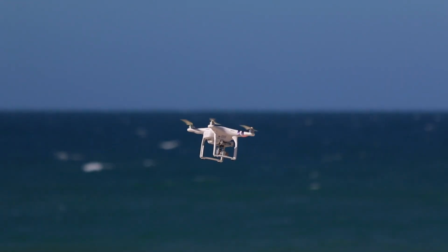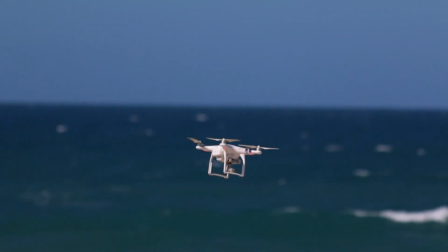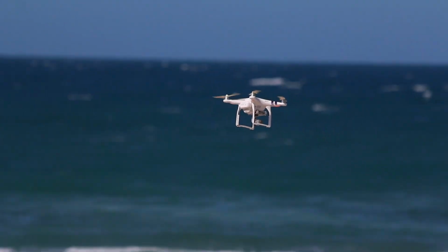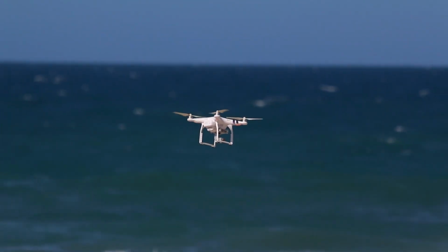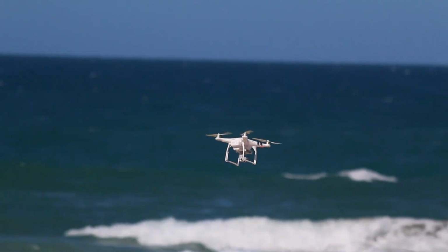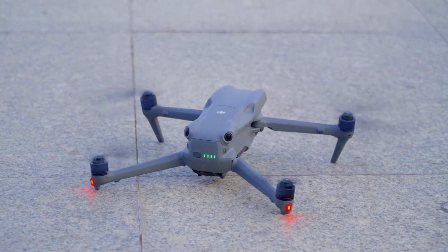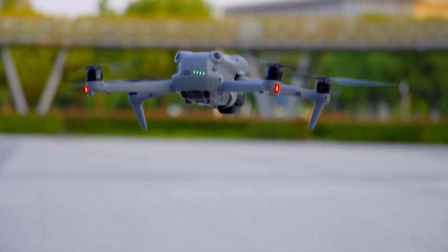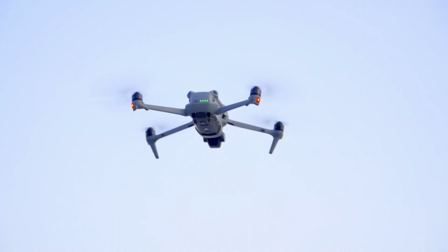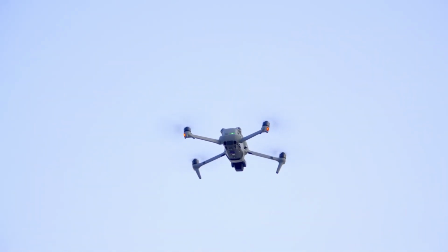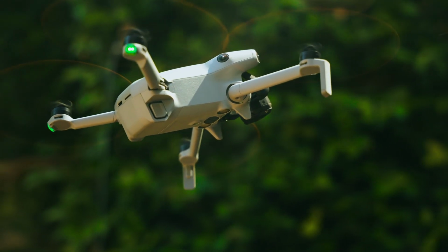Roll works the same way but sideways. Want to go left? Speed up the right motors, slow down the left motors. The drone tilts left. Instant sideways movement. And yaw, that's rotation. The two clockwise spinning rotors have more momentum than the counterclockwise ones. That imbalance creates a twisting force, and the drone rotates.